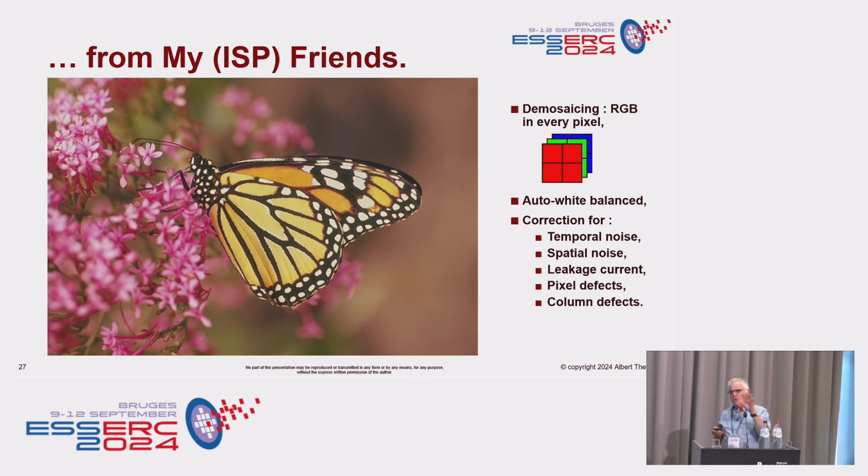You will be surprised to know how many pixels are being corrected in your mobile phone image sensor. Defect columns, with our consumer eyes, we do not even see that people are correcting defect columns. And at this particular moment, in the medical world, they were refusing for a long, long time correction of defect columns. But these days, even in the medical world, people accept and correct defect columns. So that all took place over here in the correction of this image. But you don't see any defect pixel anymore. Right? You don't see the effect of any defect column anymore.